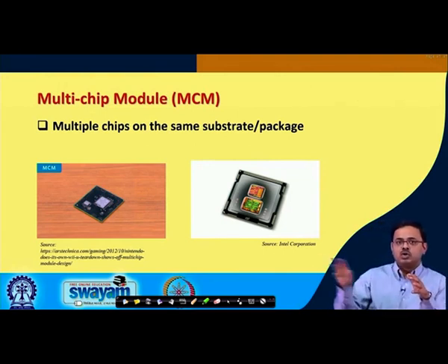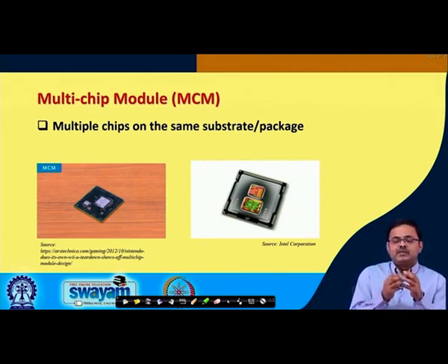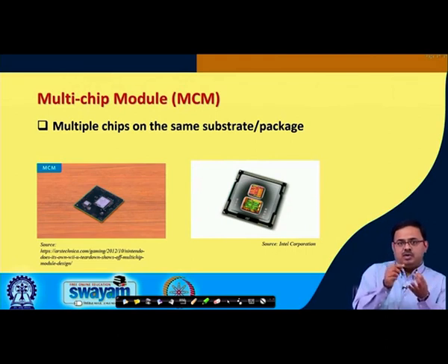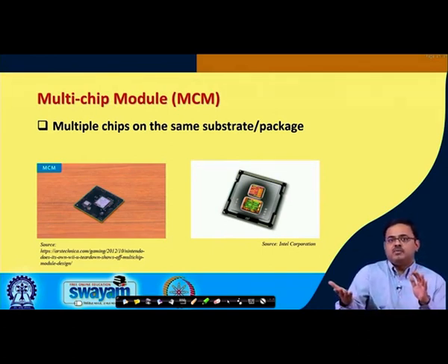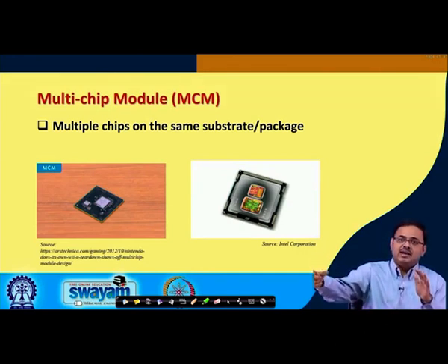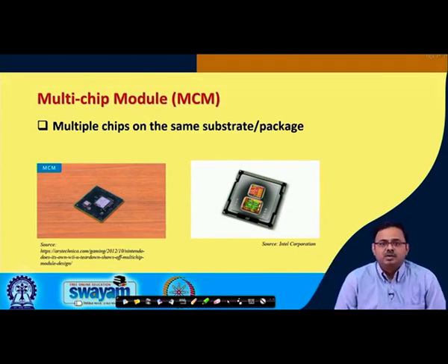If the CPU has to talk to graphics, the signals have to pass from the CPU through the silicon bumps in the BGA onto the substrate, wiring traces on the substrate, and then through the socket, whether it is a pin grid array or a ball grid array directly attached on the motherboard, whatever it is. Through another layer of interconnections into the motherboard, then through the motherboard and another layer of interconnections to the substrate of the second die, and then inside the substrate through another layer of interconnect to the second chip, right.